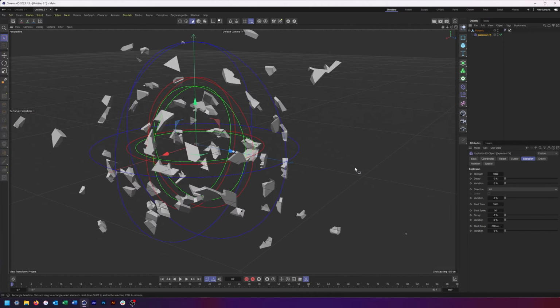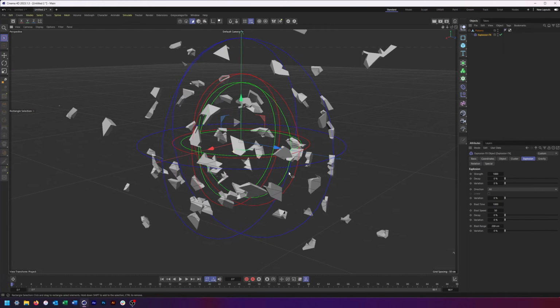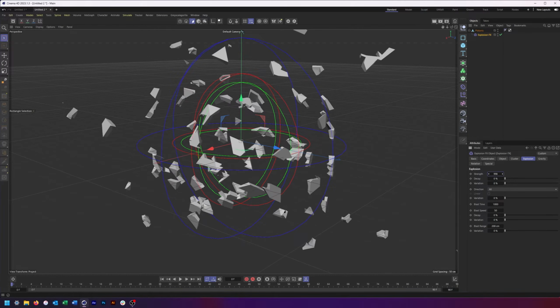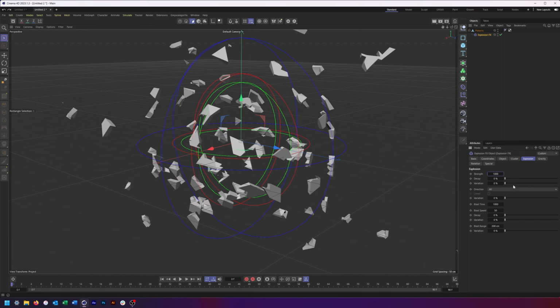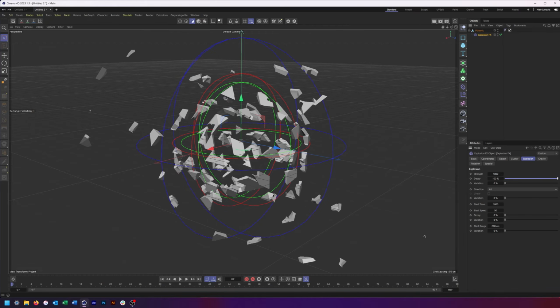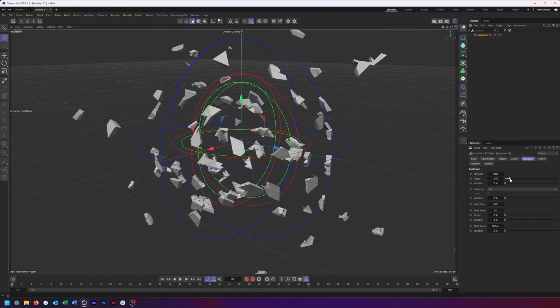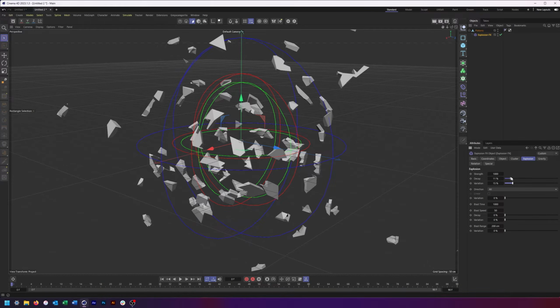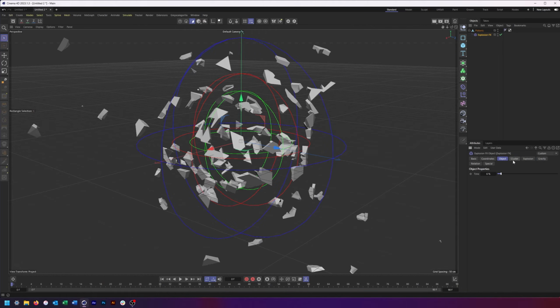Next up, we have the explosion section. We still have a couple of those sphere fields to talk about. We'll get to those here shortly. Strength, all right, for the overall blast. So, once again, controlling how far, how fast these are going to go. You can control the decay, which is how fast that strength goes away and gravity starts to overcome it. Things will start falling quicker instead of going out further and then falling down. And once again, variation. So a little bit there, probably not a bad thing. Too much decay, though, I'm not sure I really like the way that looks.